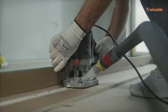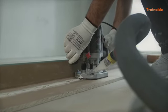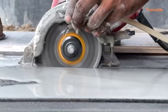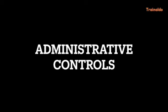Engineering controls. Next, we apply engineering controls to isolate workers from hazards. For example, if a construction task involves cutting concrete, install dust extraction systems or use wet cutting techniques to reduce airborne silica dust. Administrative controls.